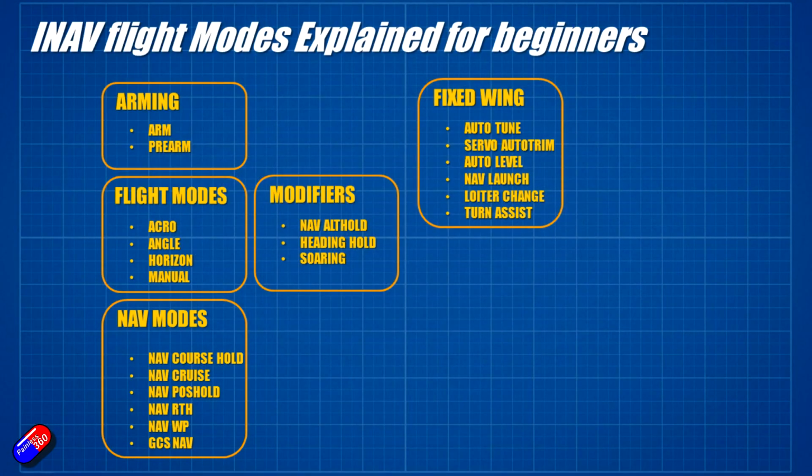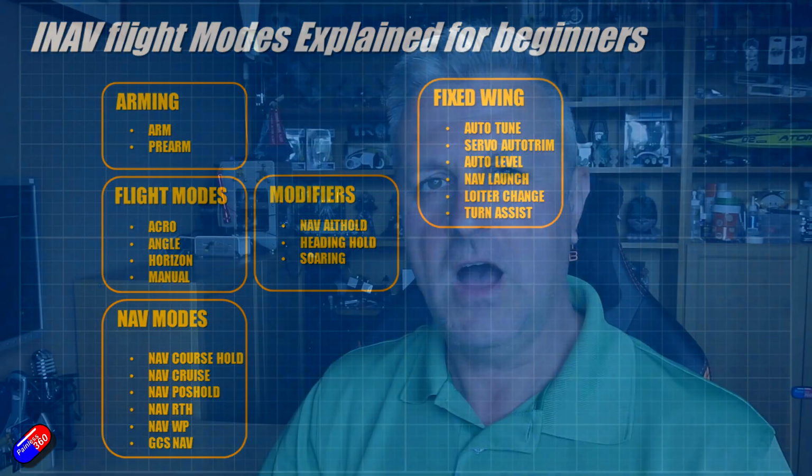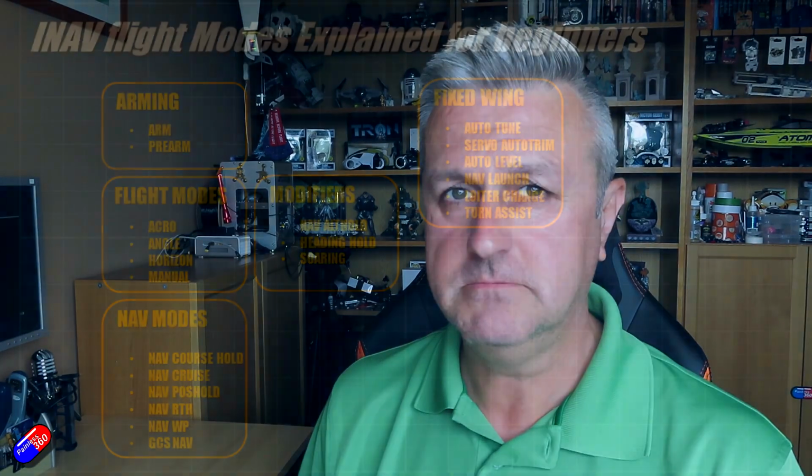Once it's set, you can turn it off, INAV will save it, and then you probably don't need to visit that again. In INAV 5.0 and onwards, you are able to adjust that value slightly using the radio, but historically it was something you had to land and play with. But auto level will let you set that, and auto level, trimming the servos and doing things like the auto tune are 3 of the things that I do on my maiden, and then I never touch them again.